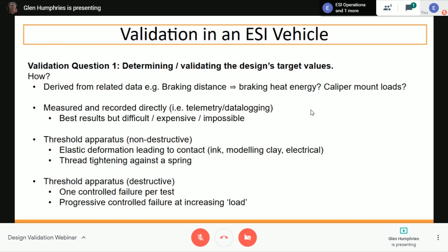Okay, these are pretty broad ranges compared to the sort of detail you'd hope to get out of telemetry. But compared to absolute guessing, these are pretty concrete numbers. If you can say without guessing that the drive shaft never sees more than 600 Newton meters, that's a solid starting point to start designing your shafts around that value.